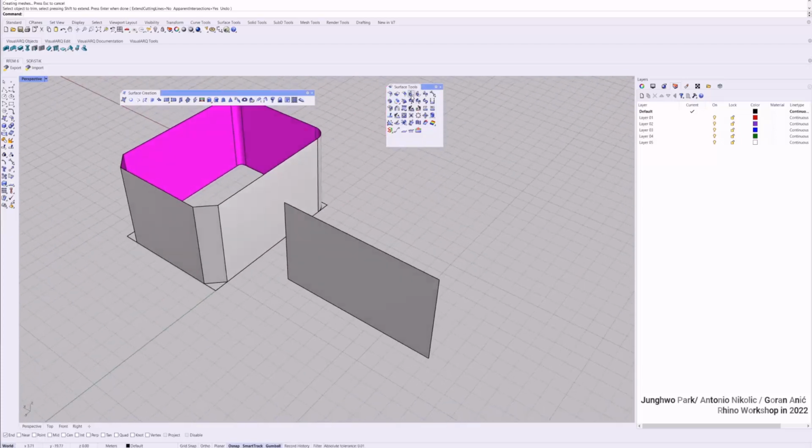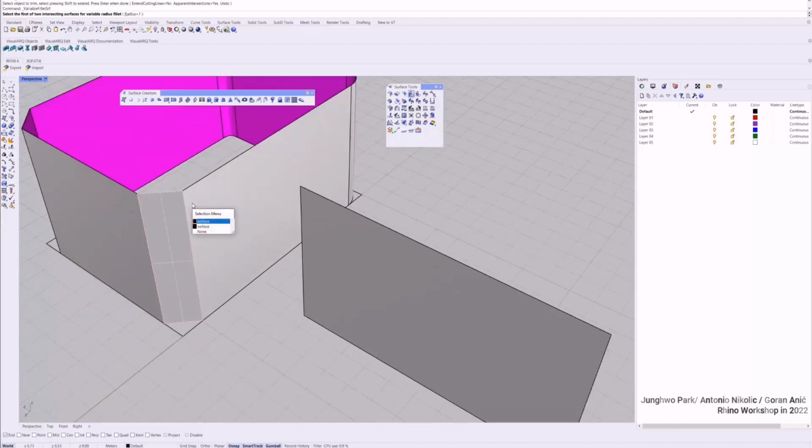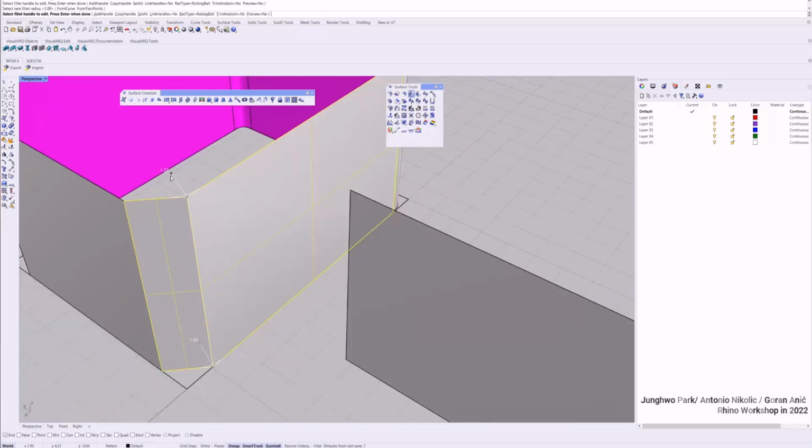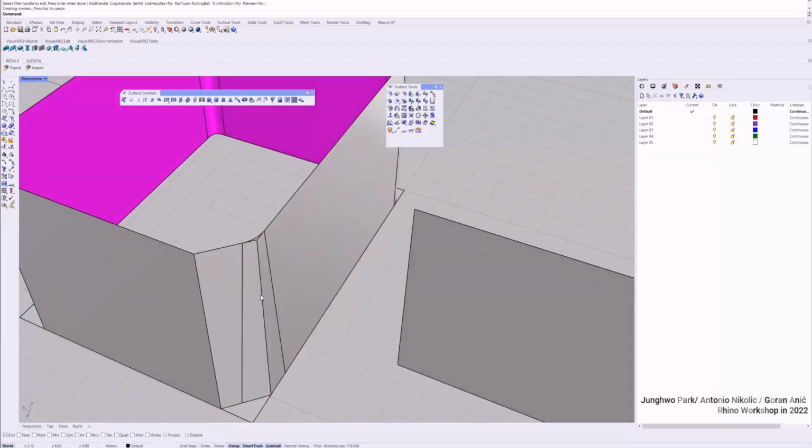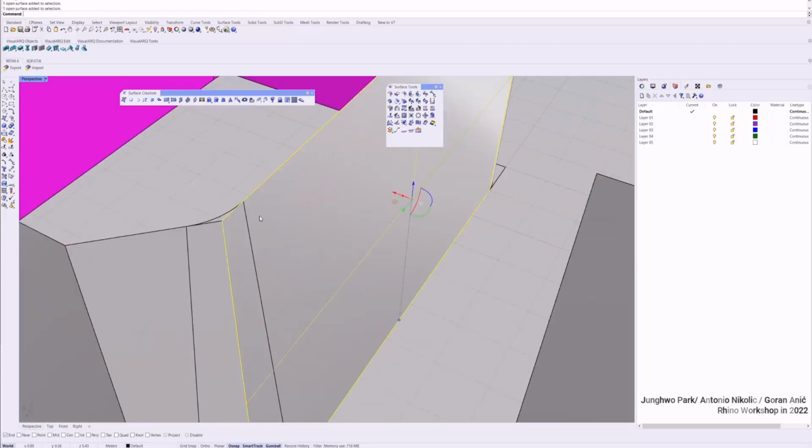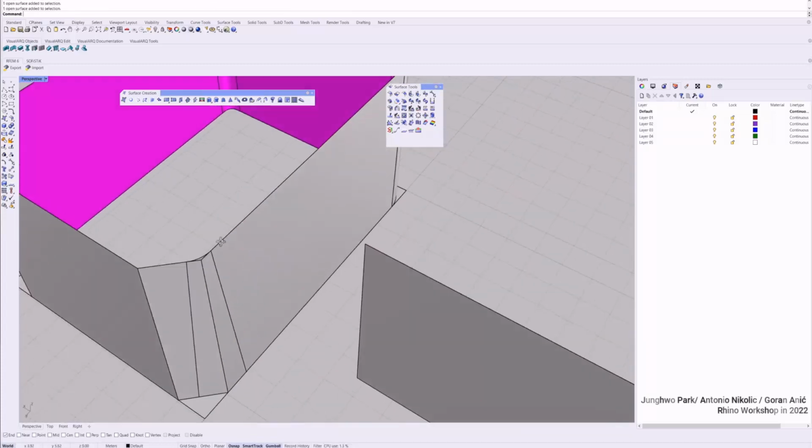Nice. And chamfer, we did. Variable Fillet Surface. So you can fillet with a variable radius, which means I can choose here and change the width with this grip. If you select, then you can type the number. For instance, here let's say 0.8, and you can click here and type 2 meter, and you see the preview, and when you hit enter, this is the result of your variable fillet.